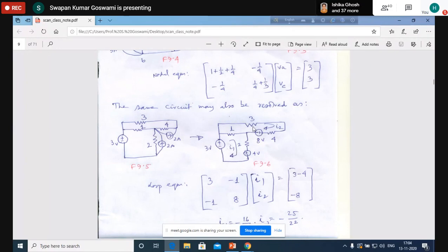Similarly, for the second loop, we have 8 volt source. Okay, here this is the direction of current clockwise, I2. I2 you see that is entering through the positive terminal, but natural current of this 8 volt source should go out of the positive terminal. So they are opposing each other. Therefore, 8 volt will be a negative source here, and it has become negative.